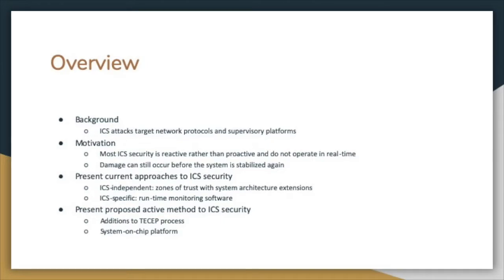The novel technique proposed in this paper utilizes TECEP, which stands for Trust Enhancement of Critical Embedded Processes. It's a design process that includes malware mitigation in the control system development process. Additions were made to the TECEP design flow in the context of industrial control systems, leading to the design of a system-on-chip platform for ICS malware mitigation.